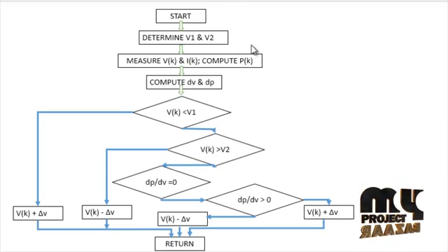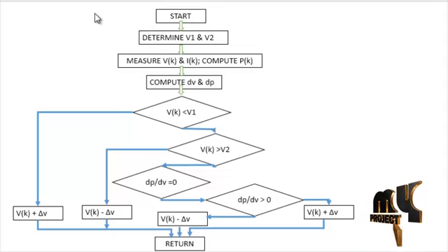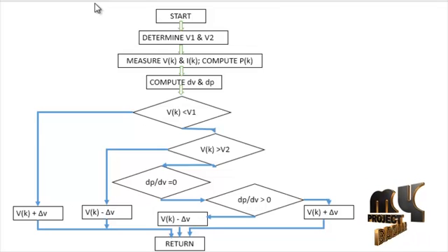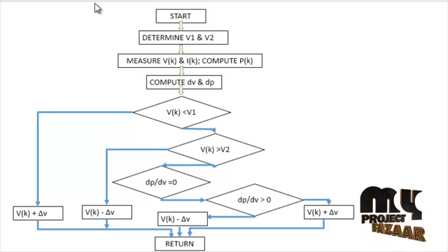This is our flow diagram. In our proposed design, we use a solar panel to get the power. Generally the solar power output is very low due to the irradiance conditions, so we need to increase the output power. So we use a maximum power point tracking algorithm. Various kinds of algorithms are used. We designed an improved incremental algorithm. This is the corresponding incremental algorithm flowchart.